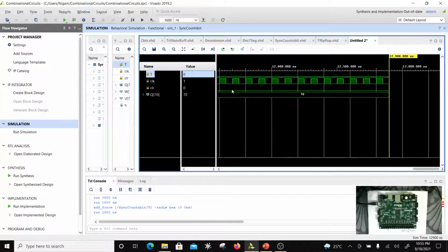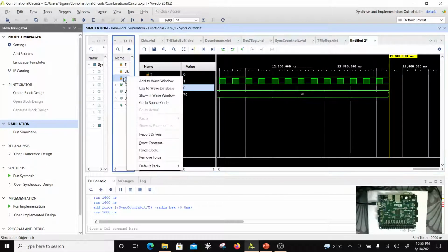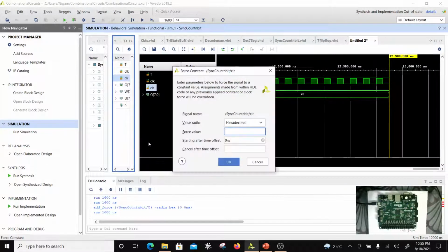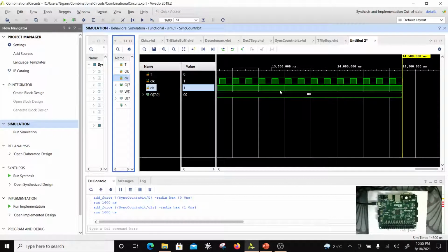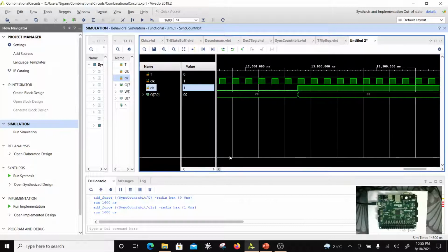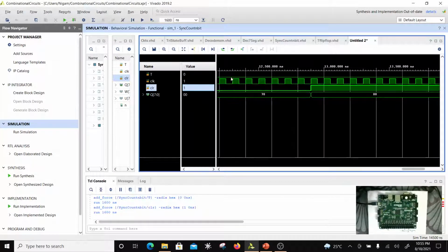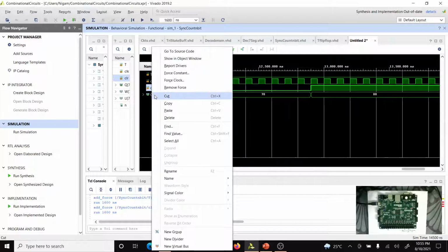freezing the toggle. And same thing if I was to force clear to 1 anytime, because this is asynchronous, it will immediately turn to 0 irrespective of the clock. So irrespective of the clock, the output has turned 0 as soon as you bring in clear. And if you take clear off, it will start counting again provided T is high, right?